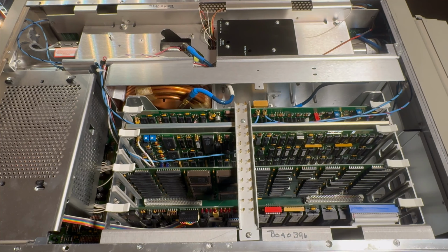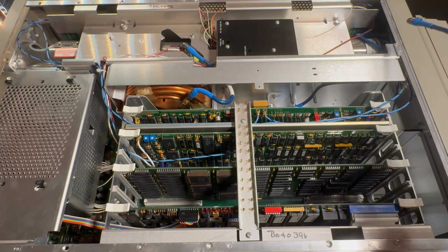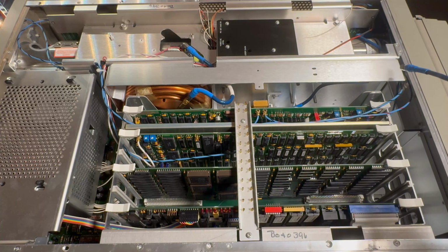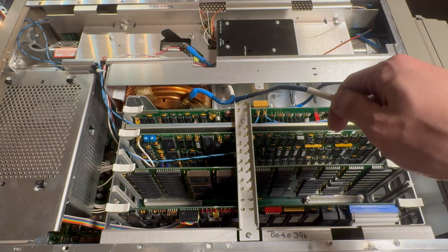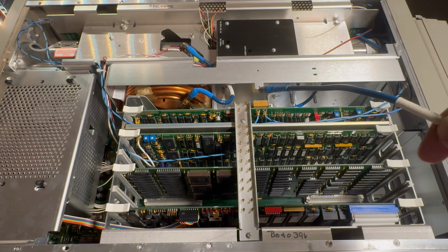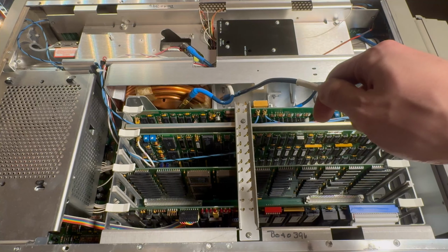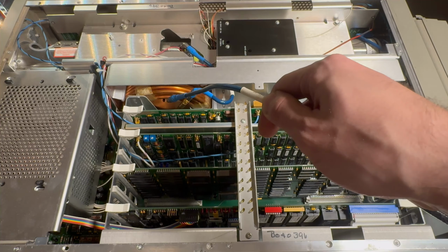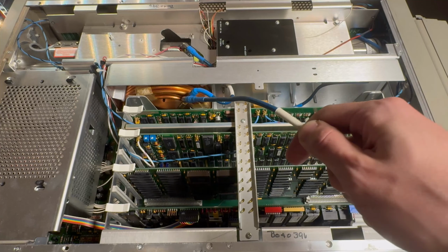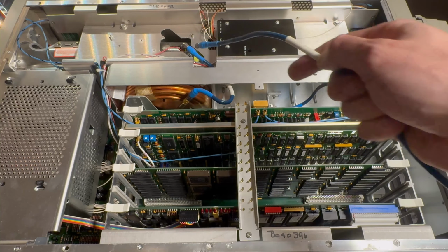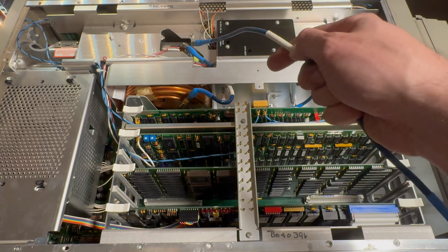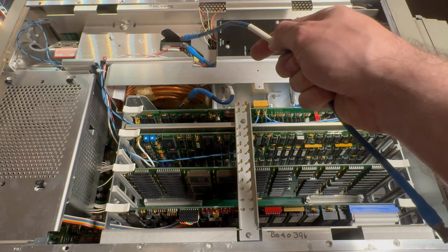Okay, this video is getting long enough, so I'm gonna try and speed through this area. So what we have is the input comes from around here somewhere. It goes through this cable and it feeds into this bit here, which is the trigger pickoff. One cable comes out and goes to the trigger board here, and the other one continues into a rigid coax, which is this copper tubing, which is the delay line. The delay line then terminates into another very fancy cable like this one, which is also a bit of delay line if you think about it, and goes into the vertical deflection plates of the scan converter.